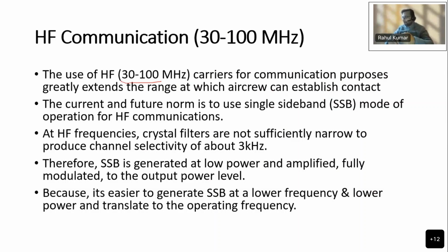Okay, now the current norm or trend is to use single sideband, SSB, for high frequency communication. Okay, now for the high frequency range, the crystal filters are not sufficiently narrow to produce the channels, right? We need frequency multiplexing.